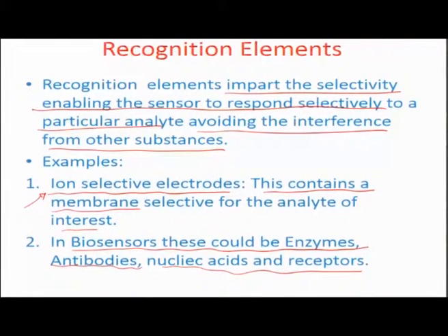And so if I wanted to immobilize the surface of a sensor which otherwise is a pH sensor, and which would be able to record the gluconic acid, which is actually a weak acid in this particular case, in terms of the excess hydrogen ion concentration that increases because of its formation. So wherever on the sensor surface we need to trap glucose, we somehow immobilize the enzyme in a manner so that it selects only the glucose molecule and creates a change in pH only based on catalyzing the glucose molecule. So, this could be an excellent example of a biorecognition element.